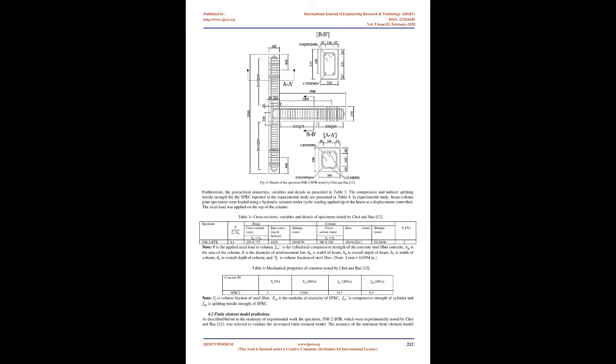Due to this, a compressive constitutive model of SFRC that differs from the normal concrete compressive model was still employed. In this study, an attempt was made in the validation section with different SFRC compressive stress-strain models, and the model proposed by Lee et al. [31] was adopted. Based on this constitutive model, the behavior of the SFRC was assumed to be linear elastic up to reaching 0.4 of the compressive strength. After this point, the plastic behavior was defined using the following equations.